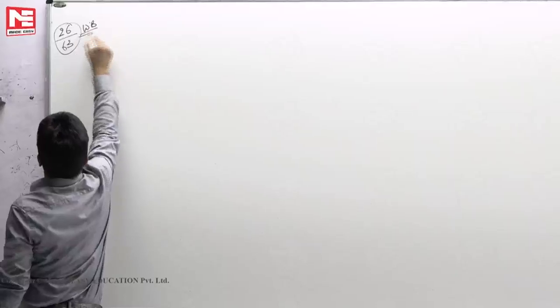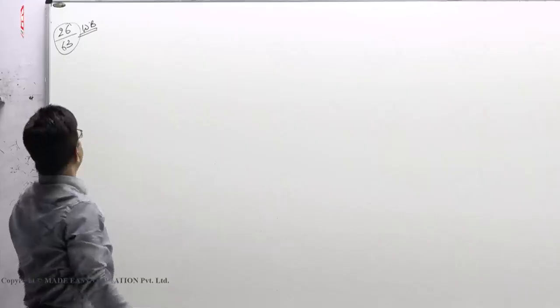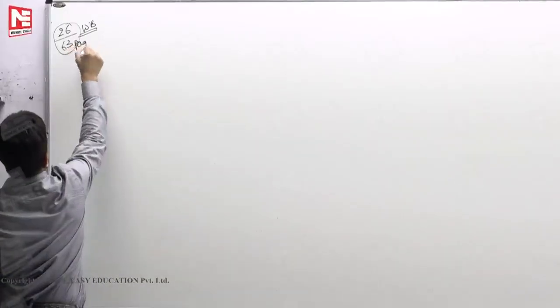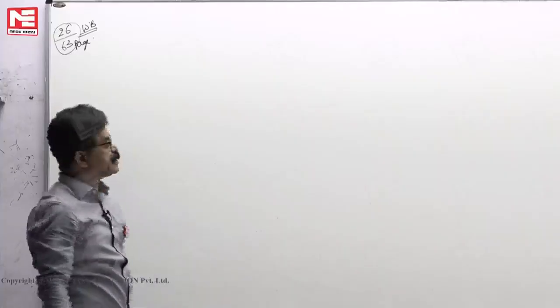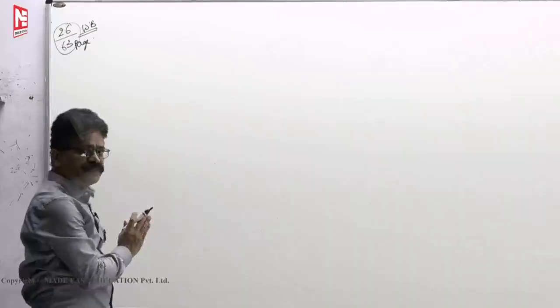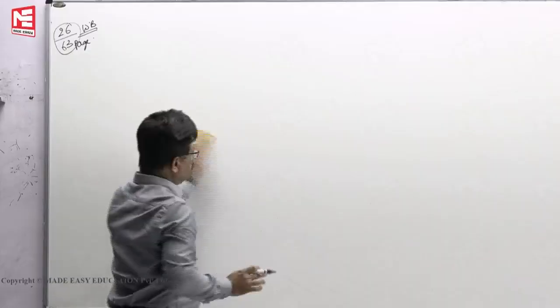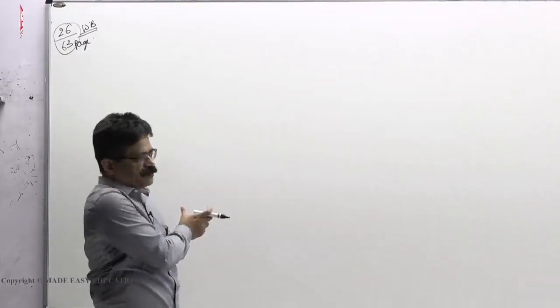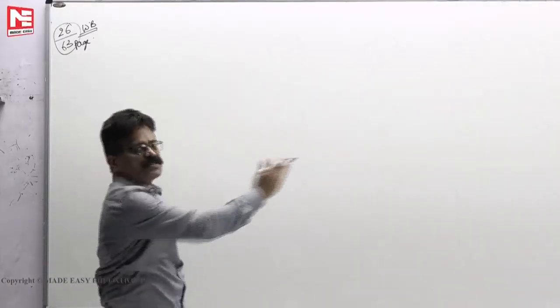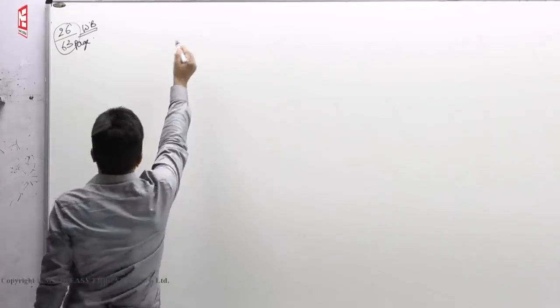Okay, now let us see one question. In the workbook, the 26th problem, 63rd page, there was a question like this. A UDL shorter than the span is moving on the beam. How much of UDL should cross C to get maximum bend moment at C? In the earlier problem also, when you have taken 1.2 meters here, you got it. That means UDL should cross the 1.8 meters in the earlier case. Now, how much it should cross, we will see.